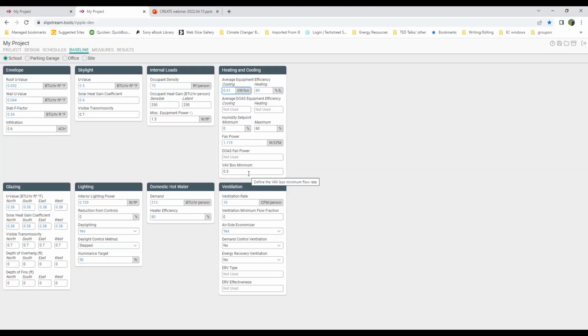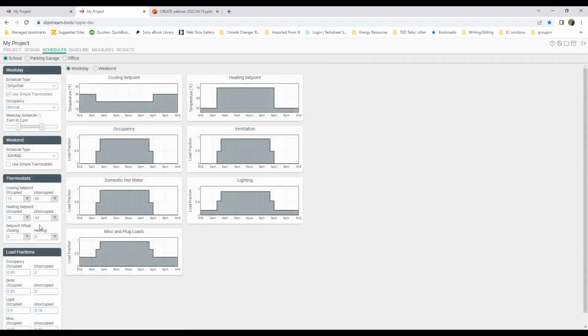If you have facility staff on site, then having the facility staff come and weigh in with the students to help them understand what their problem is, like what are they seeing? Are there hot calls and cold calls? Do they get that a lot? Which means there is something not quite right with the mechanical system. So can we change that by changing the set points in the building? So again, changing the set points and the setbacks. If the building is not occupied at night, are we doing setbacks during the unoccupied periods?